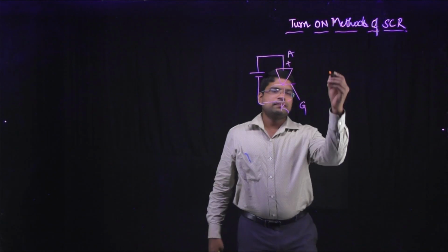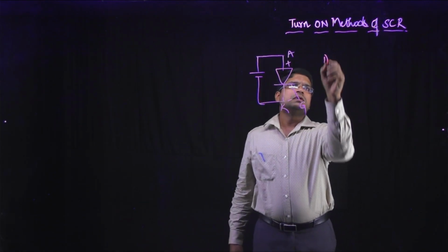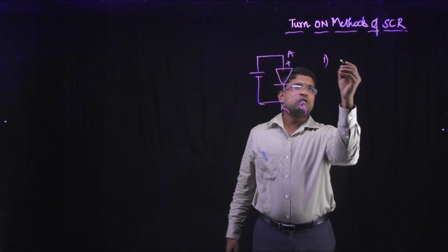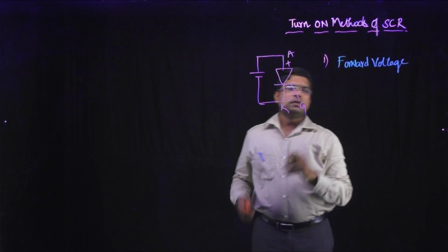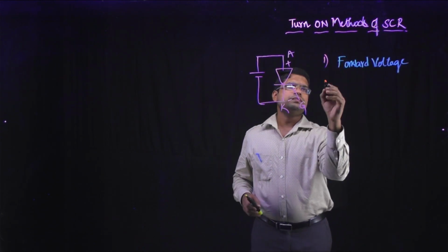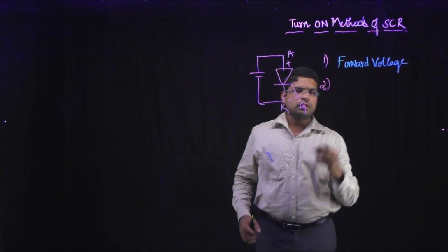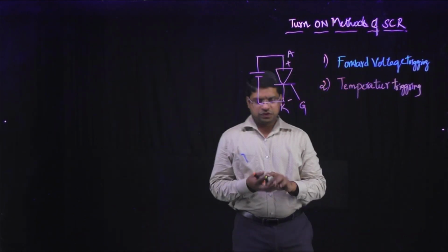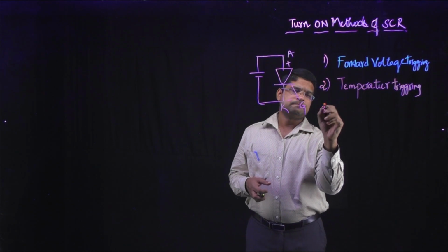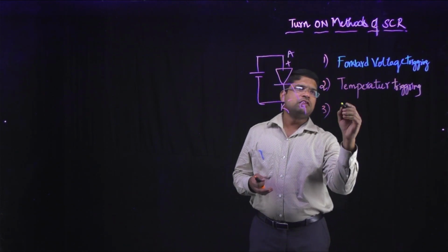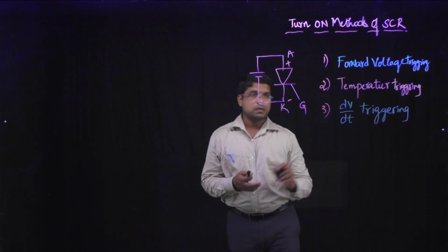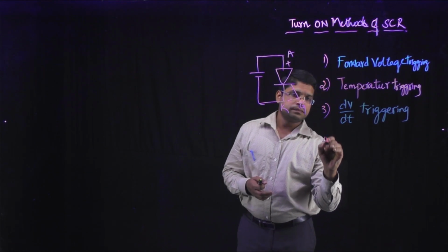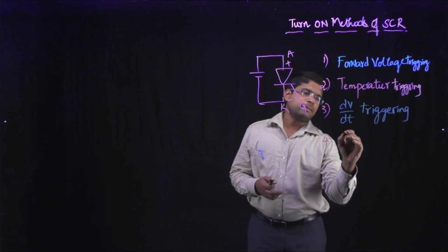Number one, forward voltage triggering. Number two, temperature triggering. Number three, dV by dt triggering. Number four, light triggering.